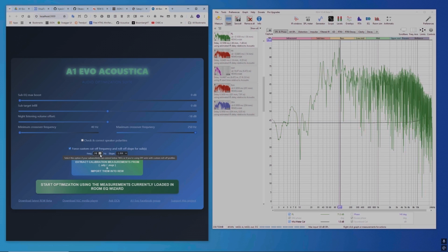So here you can select roll-off frequency, goes down to I think 10 minimum, and roll-off shape also, from Butterworth to Linkwitz-Riley and Bessel and what have you. So you have all these options. This is quite complex, but people who know their subs well will understand what is being done here. Normally you don't need to use any of those. That's all the options in it.